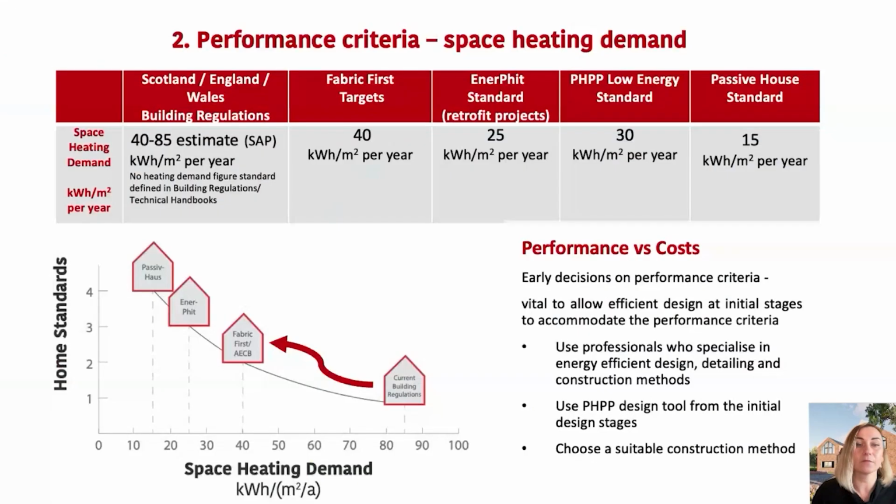So for us to be able to talk about the design elements, we need to answer the question of what thermal performance the design of your home is trying to achieve. The space heating demand figure is the commonly used metric to establish this. Just for those of you who are not familiar with the term, space heating demand is the amount of energy we use to heat or cool the building.